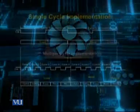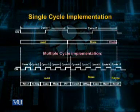Some other instructions may be completed in 4 clock cycles or 4 steps, like the register type instructions or the store instruction, whereas the load instruction requires 5 clock cycles to complete the operation. Now, in order to evaluate the performance of a single cycle data path versus the multi-cycle data path, let us consider an example program.